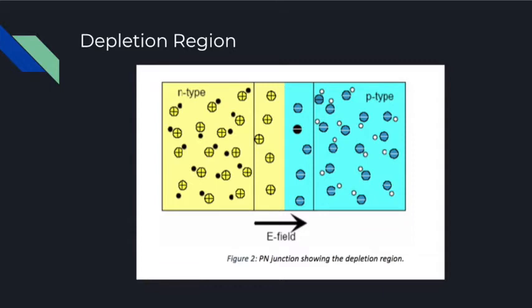This depletion region can grow or shrink, and that depends on the potential and which way it's going. And when the depletion region grows, it creates a stronger electric field, which then makes it almost impossible for current to go through it. This is why current can only flow one way through it, which is a key part of the full wave rectifier we looked at earlier.